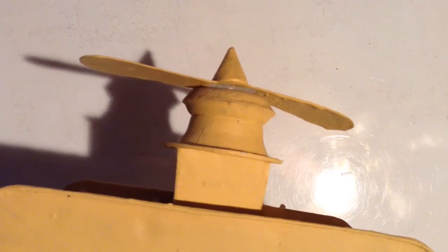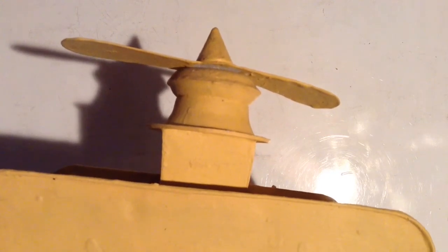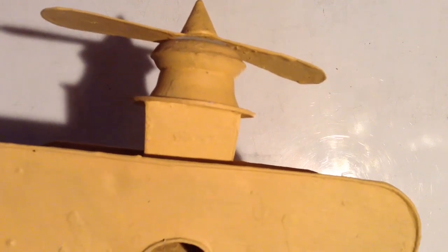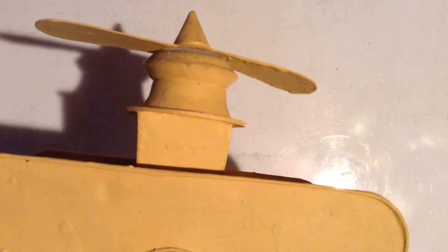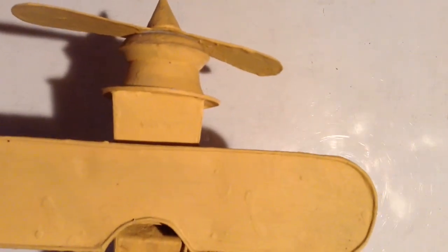So using the controls of an airplane to change the pitch of the airplane causes gyroscopic precession that turns the airplane's nose left or right, and using the controls of an airplane to turn the nose of the airplane left or right causes gyroscopic precession that changes the airplane's pitch.